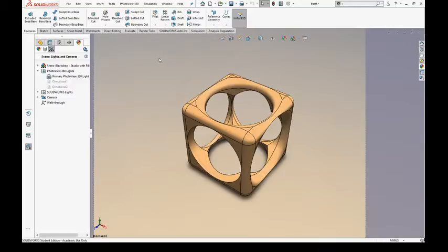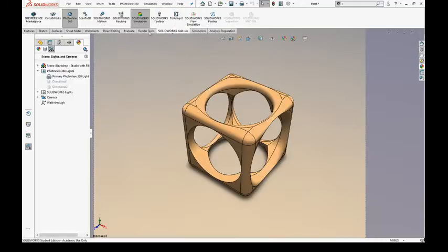What I'm going to do now is go into my render tools. Now, in order for this to work, I need the SolidWorks Add-Ins tab to be on my screen. If it's not there, you need to right click and select it from this list. Sometimes in SolidWorks your screen can look a little like this, without a render tools tab and without an add-ins tab. Just right click, choose add-ins, right click again and choose render. And you've got to make sure that when you're in your SolidWorks add-ins tab that PhotoView 360 is turned on. We don't need SolidWorks Simulate on, so I can turn that off.